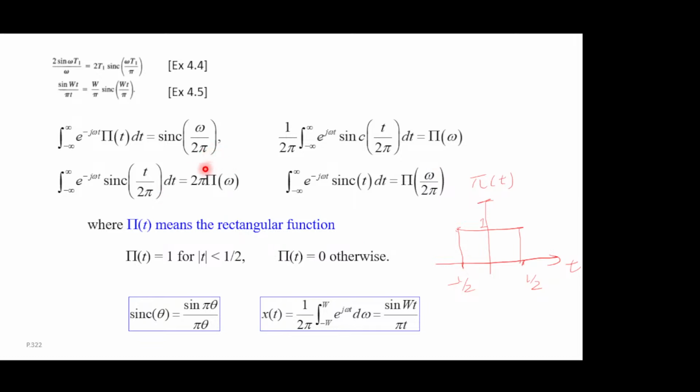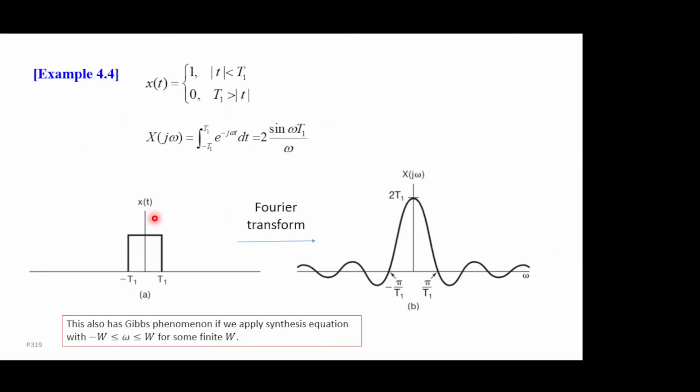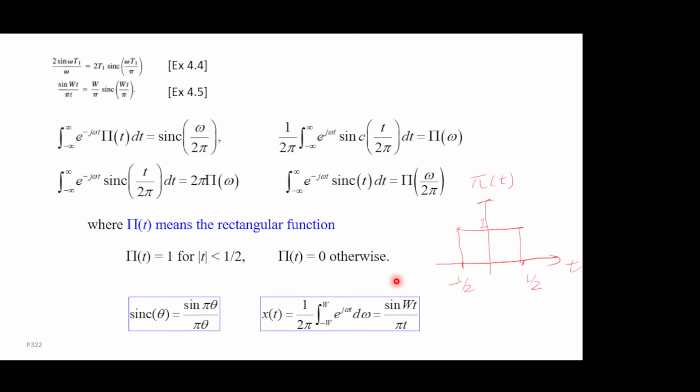And we can write all our previous results as a differently scaled sinc function and a square wave function. For example, I believe the starting point is kind of here. We can transform a square wave function into a sinc function, and that will be this equation, although here we don't have the t1. But anyway, if we choose t1 as 1/2, then this is just the Fourier transform of the square wave function, and it becomes the sinc function.